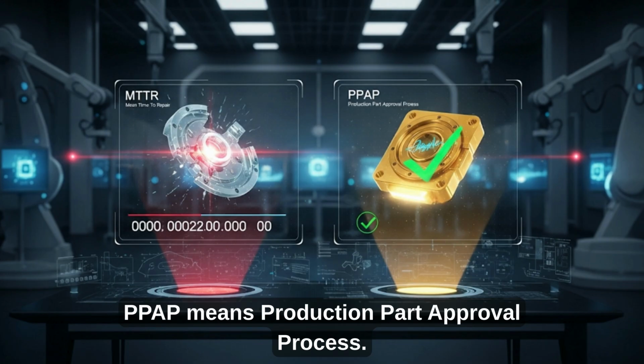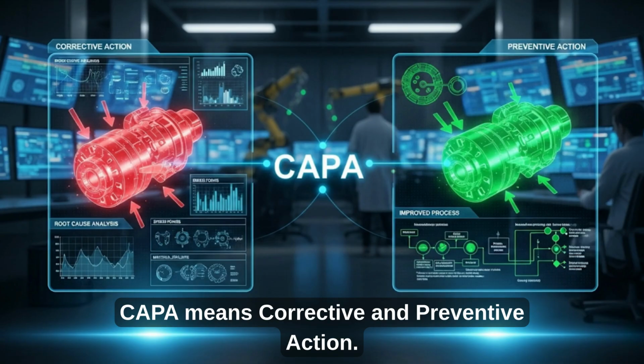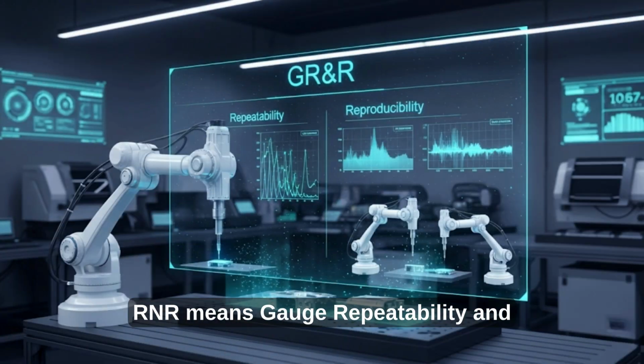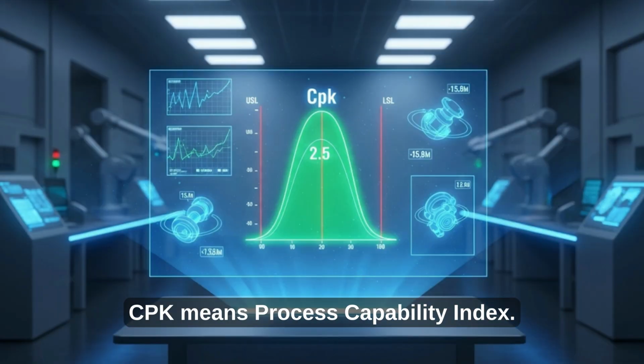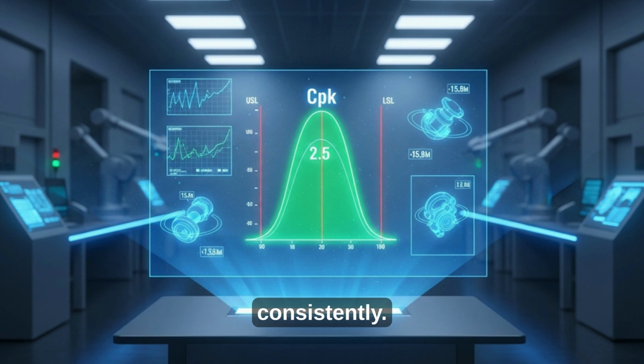PPAP means production part approval process. It is customer approval before mass production. CAPA means corrective and preventive action. It fixes defects and stops them from coming back. GR&R means gauge repeatability and reproducibility. It checks if your measuring tools and operators are reliable. CPK means process capability index. It shows if the process stays within tolerance consistently.